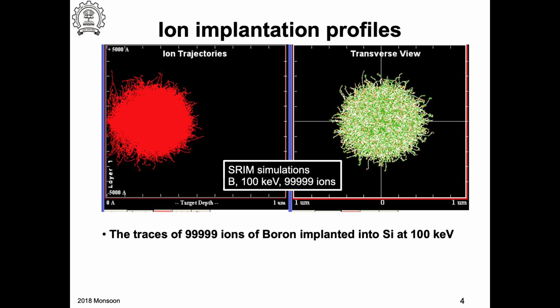So this can be fitted using a Gaussian program. The dots are the data points, and the line is the fit of this Gaussian function. Okay. So I can talk about what is called the projected range. So RP is the projected range. That is this, right? This is the mean of the distribution. And then there's something called straggle, the standard deviation. That is delta R.